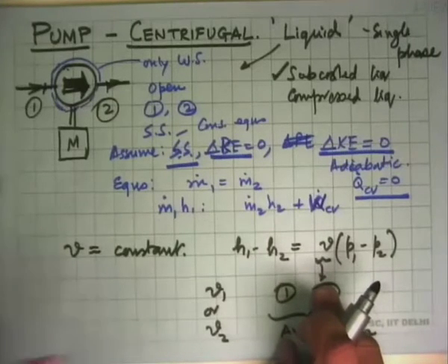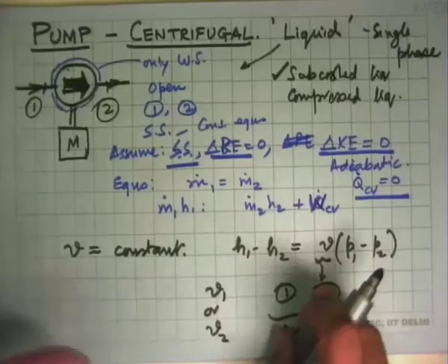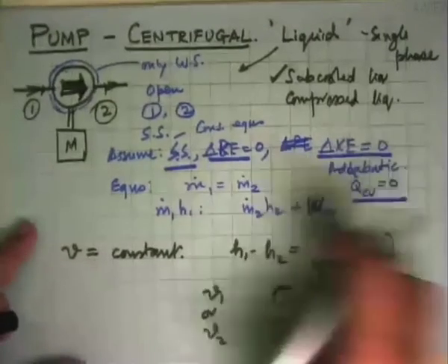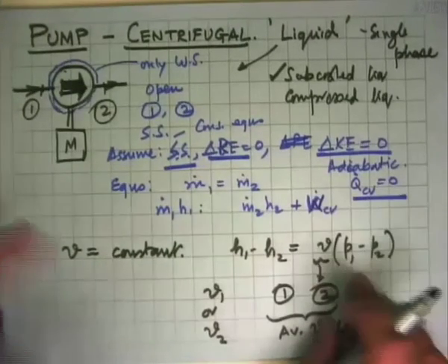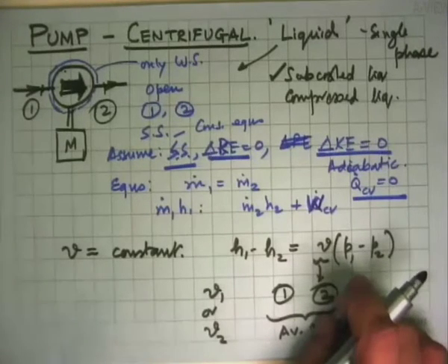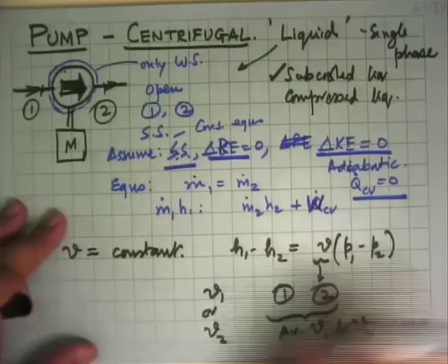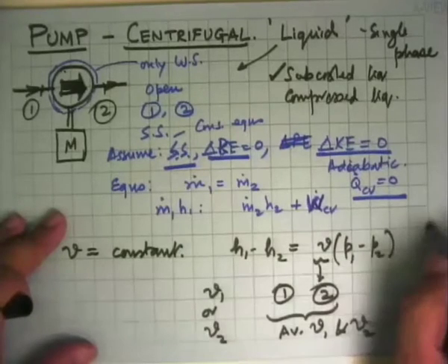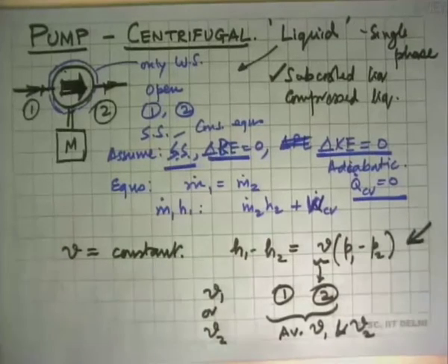In the case of fans and blowers also, where we said air is incompressible, there also approximately we can put this, otherwise we can always go in gases as Cp0 (T2 minus T1) and work out from there. That's fine. But liquids, this is the important difference.